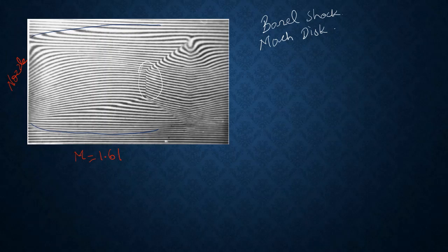So what about this particular Mach disc? It's very simple: when two barrel shock waves meet the exposed atmospheric air, we have uniform flow throughout this section. You may see that the fringes are distributed in a uniform manner. But what happens to this particular barrel shock? We have the interference pattern, that is, the fringes are not uniform in some cases.